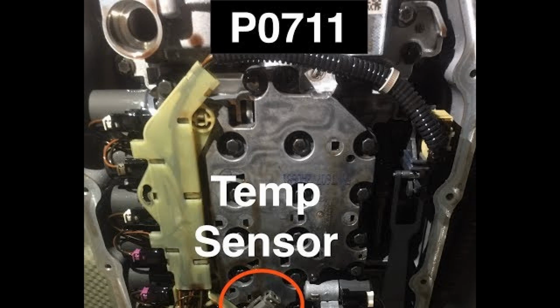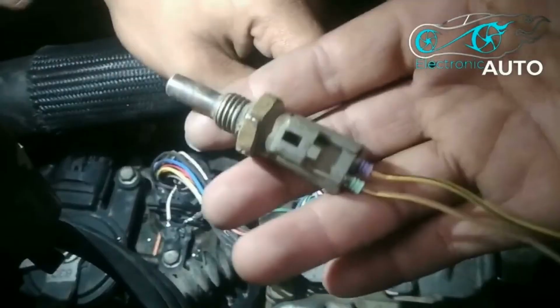This sensor is used by the PCM or TCM to determine the temperature of the automatic transmission fluid. The signal is used to determine the best shift points and adjust the line pressure. In operation, this will cause the control module, PCM or TCM, to engage the torque converter clutch, TCC, earlier and disengage the overdrive gear. This is done to lower the fluid temperature if it becomes higher than normal.